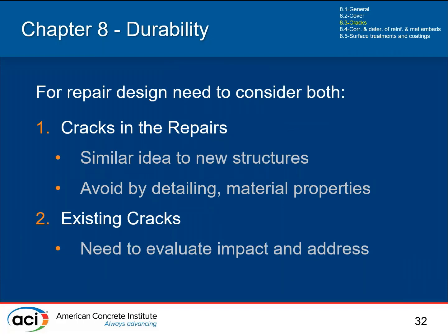But I think the important thing I wanted to start this discussion on cracks is that for repair design, it's different in many ways than it is for new design of a structure. New design, there's nothing there, so all the cracks are going to be potentially in the part of the structure that doesn't exist yet, and so you have control over that with detailing and material properties. For repair design, you're only controlling part of it, but really, the whole structure is what you're concerned with.